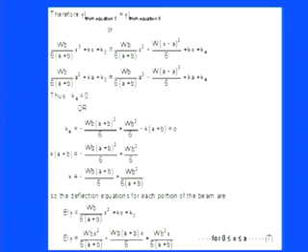By keeping those things, you have the different equations for the deflection term EI into Y. For this first section, WB divided by 6 into A plus B times x cube plus kx plus k3. By keeping those values, you have the final deflection equation for the AB portion: EI into Y is equal to WB x cube divided by 6 into A plus B, minus WB into A plus B into x divided by 6, plus WB cube x divided by 6 into A plus B. So this is a valid equation.